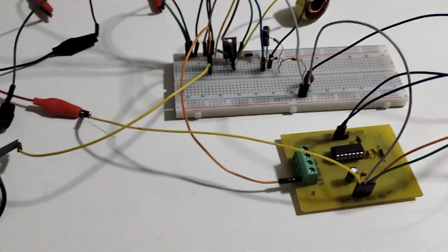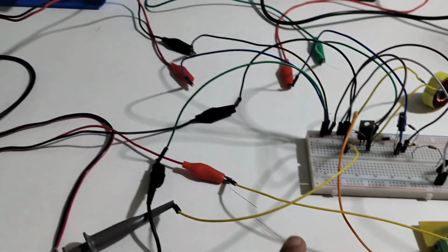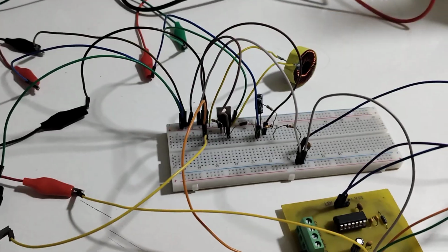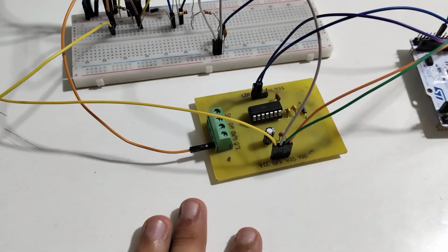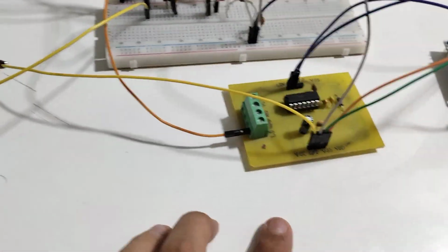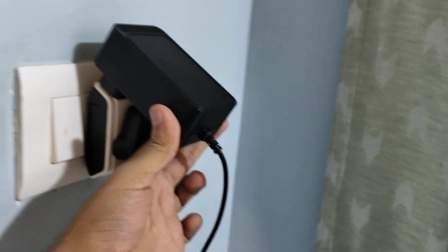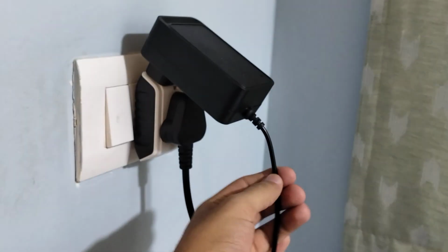And I have an upgrade since last time. For the closed loop buck, I just used one power supply for the driver as well as the power stage, and generally they avoid that because you want the driver voltage to stay constant. You don't want it to be affected by how much the load is drawing on the power stage. So the power supply today will be used for the power stage, the actual boost converter, and the driver will get its voltage from this wall brick here, a common one. You can get it cheap, 400-500 rupees. It gives a fixed 12 volts, so this should be good for that.